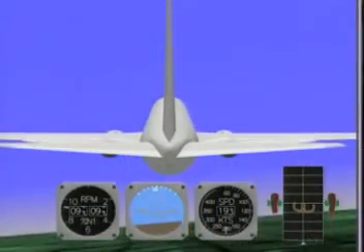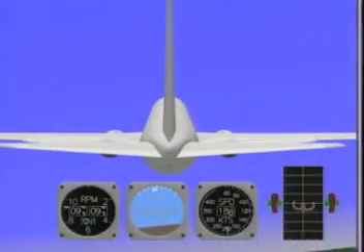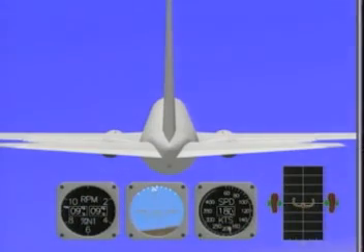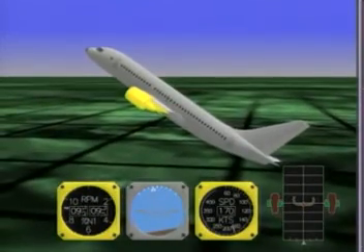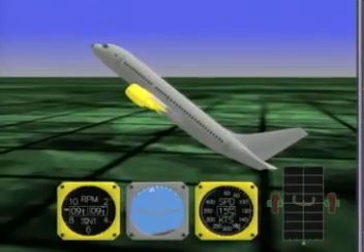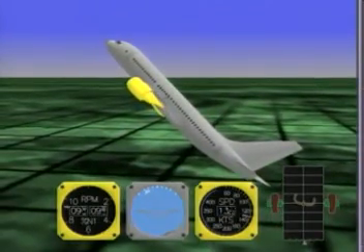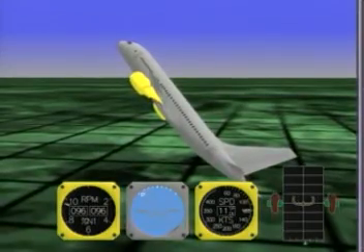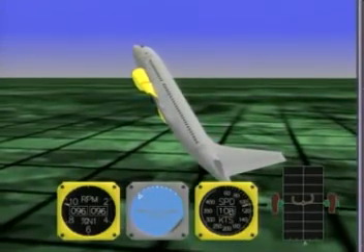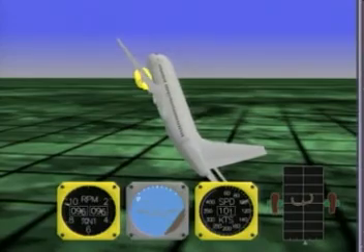At high bank angles, you may be in a nose-high attitude or a nose-low attitude. Let's look at a nose-high situation first. A nose-high angle of bank attitude requires deliberate flight control inputs. A large bank angle is helpful in reducing excessively high pitch attitudes. Unload and adjust the bank angle to achieve a nose-down pitch rate while keeping energy management and airplane roll rate in mind.